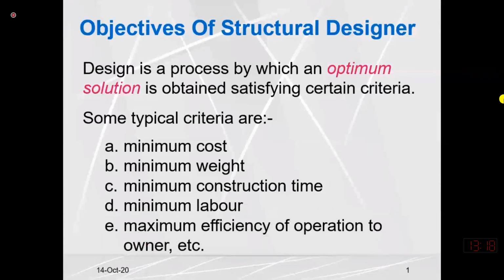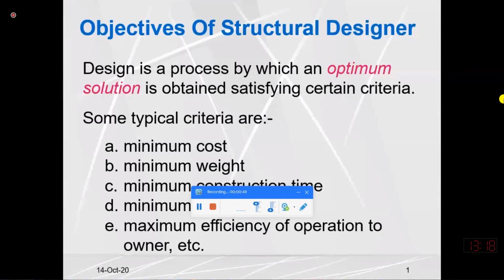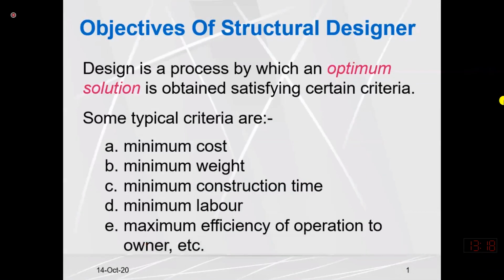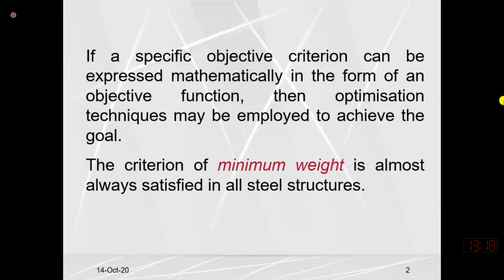So it means that if the client requires a larger clearance on the front side, we have to use larger spacing of columns. If in our usual design we are using a spacing of maybe 12 to 15 feet, maybe if our client's requirement is 20 feet or 25 feet, we have to modify our design accordingly.